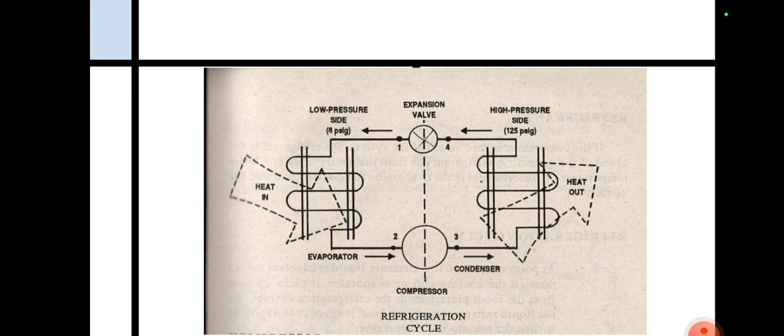At point 1, it is called the evaporator. It is a cooling coil that works as a heat exchanger. The low-pressure liquid refrigerant moves through the cooling coil. Then it absorbs heat from the foods placed inside the refrigeration cabinet. As the liquid refrigerant absorbs heat, it changes to vapor. And then, it goes to the compressor.